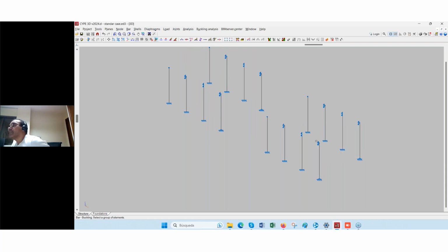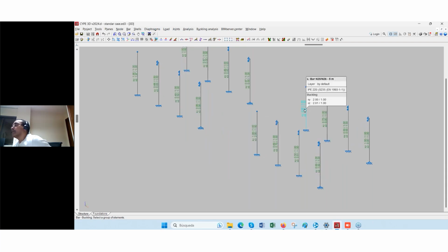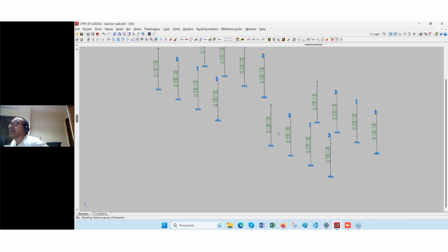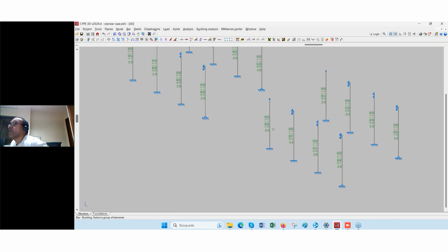So why do we have differences with the normal calculation we make by hand? The difference is the consideration of the shear deflection. So if you see that at this point, we don't have exactly the same value as a hand calculation, because normally when we make a calculation by hand, we don't take into account the self weight of the bar. In this case, I didn't take it, but the shear deformation was very important to have this small difference.